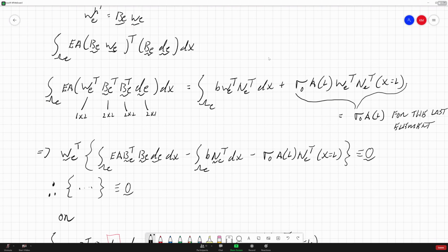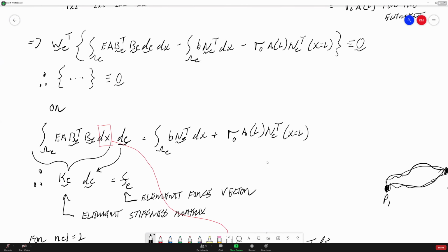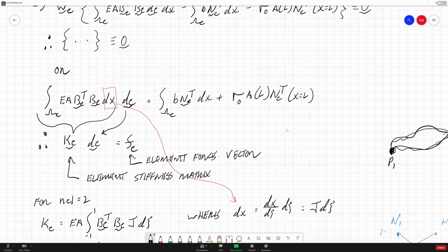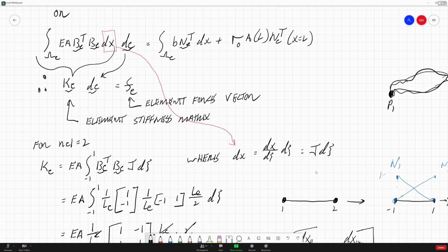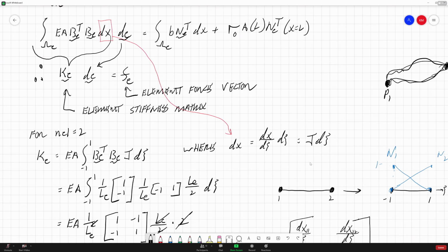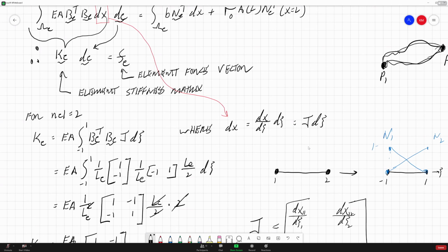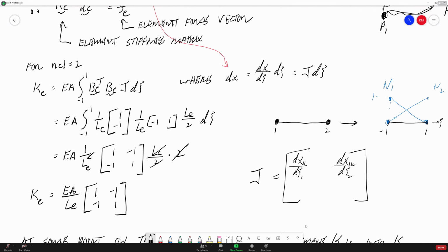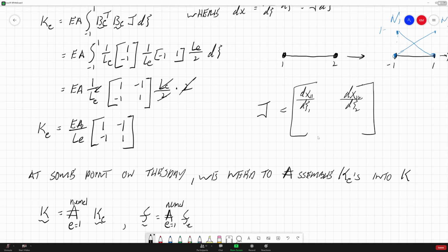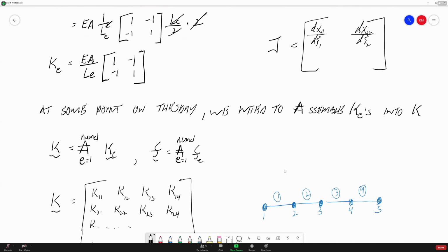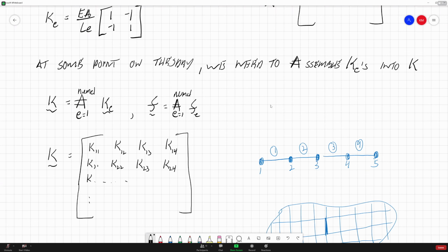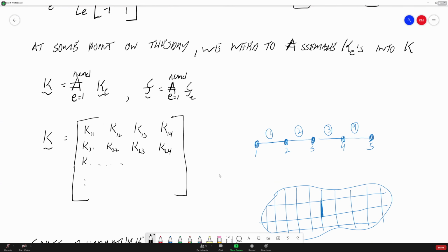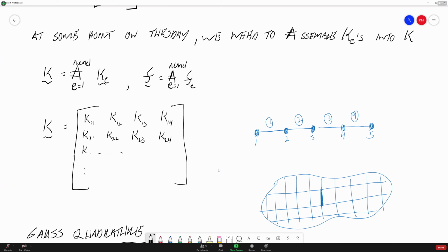And we're solving it. This is really just a differential equation that we're solving using these different methods like the Rayleigh-Ritz methods and the theorem of minimum potential energy, for taking the derivative of minimizing functions, and ultimately getting this stiffness matrix for the global system, which we saw a few weeks ago, and now we're talking about it at the elemental level.